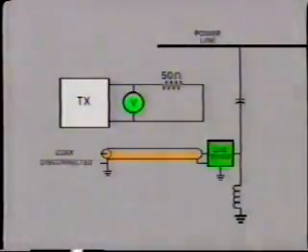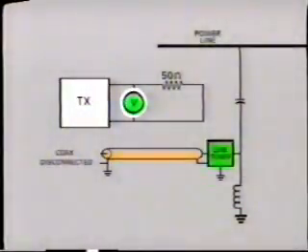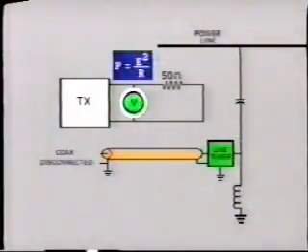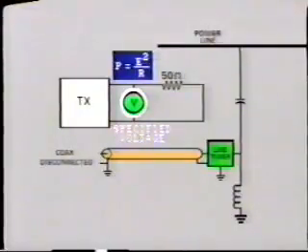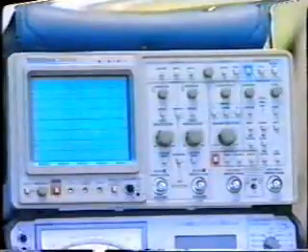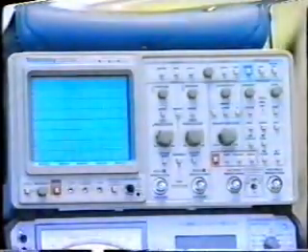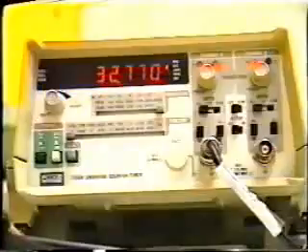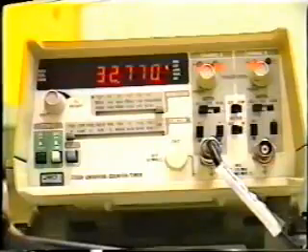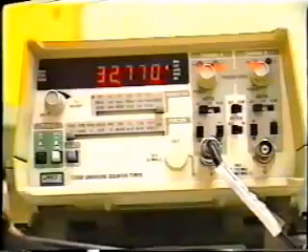With the transmitter switched on, we can measure the voltage across the resistor and easily calculate the power output of the transmitter. The transmitter is adjusted to provide the specified voltage at different conditions, for example, guard and trip signals. Often, an oscilloscope is connected to check that the output wave shape is free of distortion. A frequency counter is also connected across the transmitter output so that the specific frequencies can be checked at the same time and adjusted as necessary.